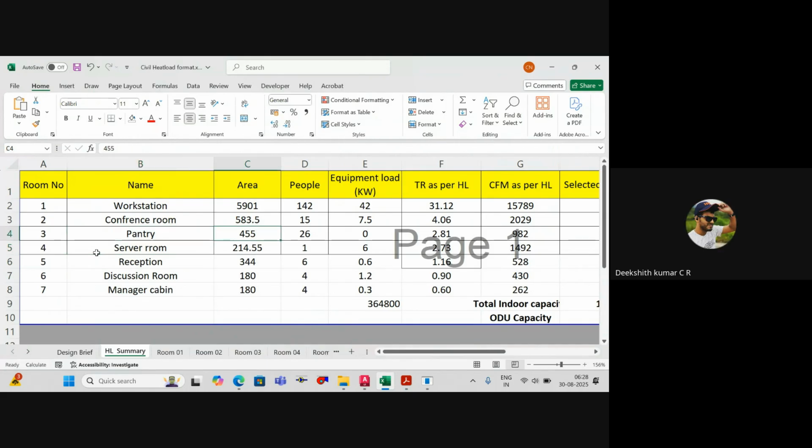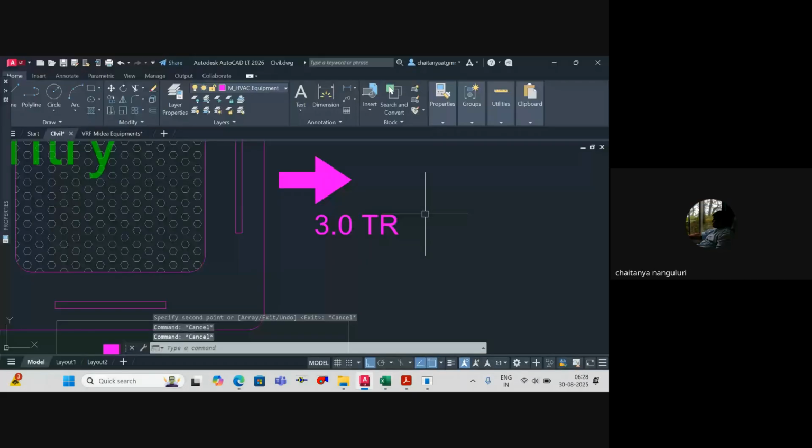Yeah, this is 3-tier pantry. Pantry is 3.75 HP. You agree? So 3.75, if I'm not wrong, is not available. 4 HP is directly available. You have to slightly increase the capacity. Sorry, 3.75 tons, right? This is 3.75 HP. Yeah. So 4 HP I have to go for.